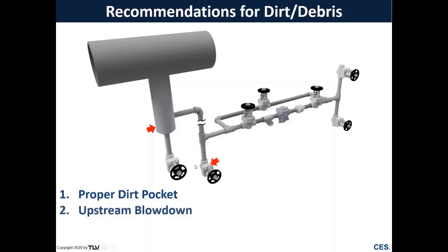The next thing is you have your upstream blowdown. This is another place where you can have the dirt collect and blow this down occasionally to get rid of that dirt before it gets further downstream into your strainer and steam trap.